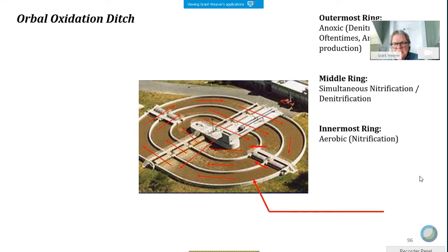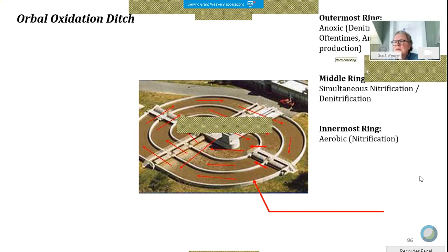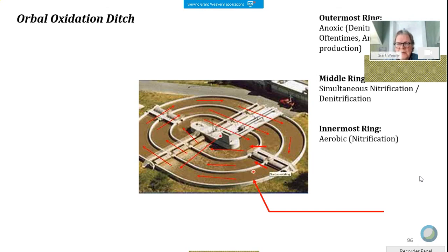And if it does, then it's no longer going to remove nitrates. So let's get my little marker tool here, which I know kind of mucks up the picture, but if we're pumping too much here, the dissolved oxygen in this zone is getting too high, and if there's a way to grab a sample as it goes into this zone, then you'll see a lot of nitrates going into this zone.